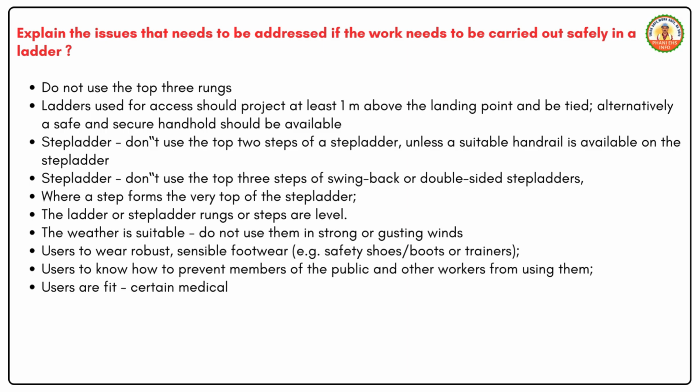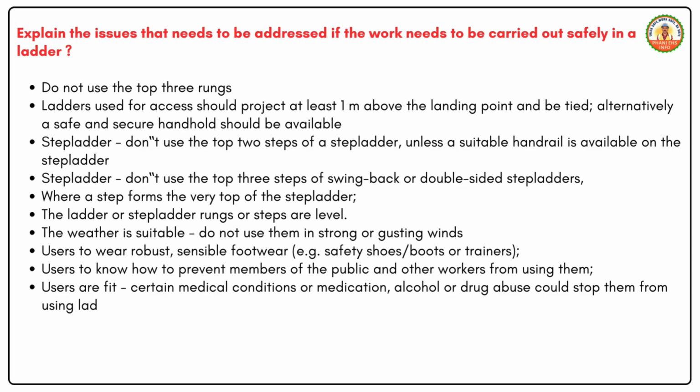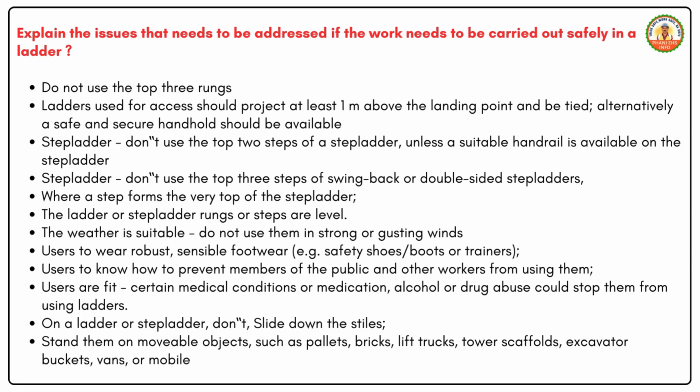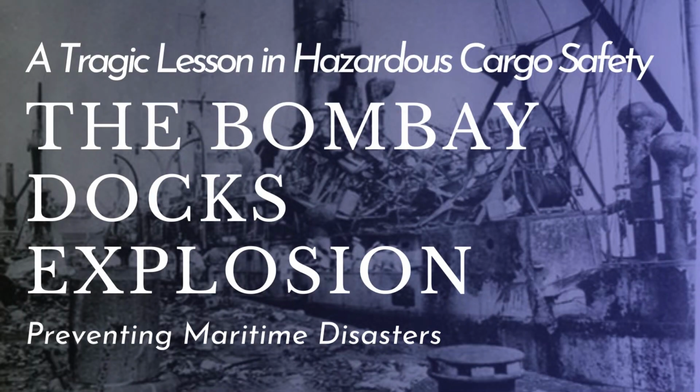Certain medical conditions or medication, alcohol or drug abuse could stop them from using ladders. On a ladder or stepladder, don't slide down the stiles. Don't stand them on movable objects, such as pallets, bricks, lift trucks, tower scaffolds, excavator buckets, or mobile elevating work platforms.